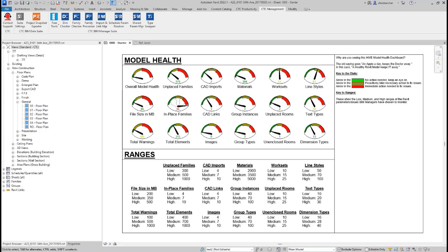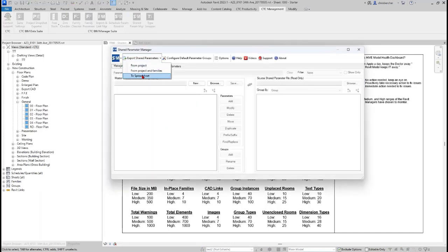Then you have, can we migrate shared parameters from a text file we don't have into our company file? So if you don't have the shared parameter file, but you have a project that is using those shared parameters, whether they were manually added to the project or with a bunch of content or a bunch of families loaded into said project, then yes, Shared Parameter Manager will either export just the ones in the project or the ones in both the project and the families. So there you have it.